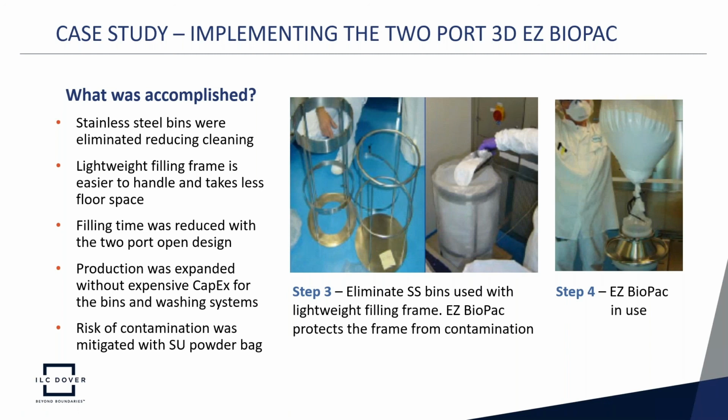Going with a lightweight filling frame is much easier to handle, much easier for the operators to work with, and it takes up less floor space. The filling time was reduced when we go with the two-port open design. We have that large target. So the production was expanded without expensive CapEx for the bins and the washing machines. And again, we reduced the risk of contamination by using the single-use powder bag. Anytime we know in the biopharma space that we can use a single-use product and go away from cleaning, then we have a benefit: the risk of contamination is reduced.